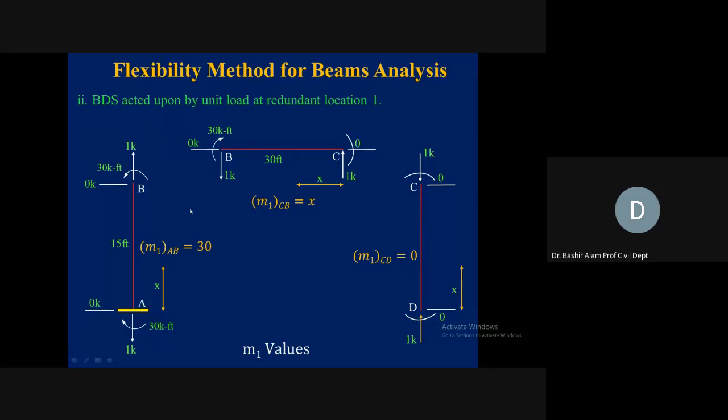Now let's put this BC in equilibrium. So 1 kip in downward direction, 1 kip in upward direction at C. Summation of Fy satisfied. Horizontal 0, moment: 30 kip-feet, it was a clockwise moment. So now this 1 times 30 is causing counterclockwise, so 30 minus 30, 0. So that is why here we have this 0.